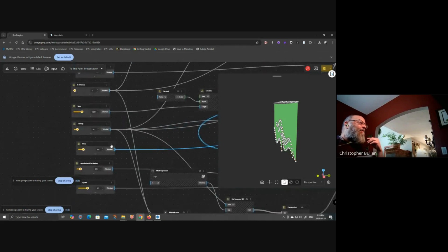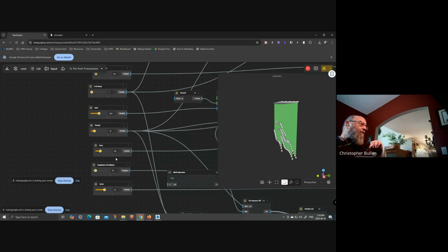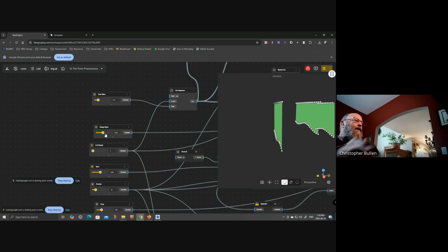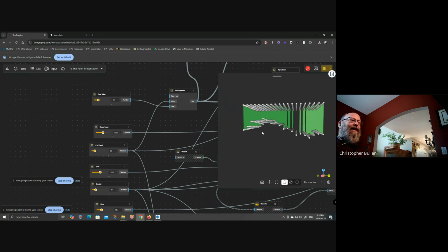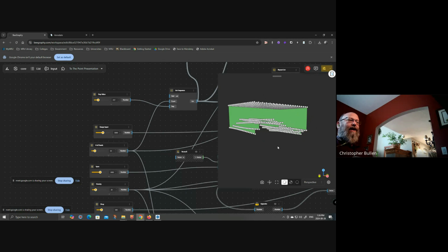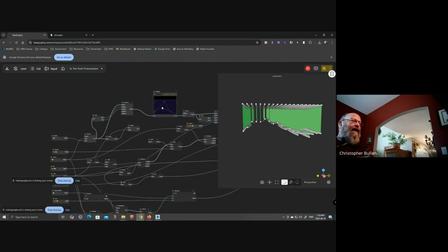Instead, for our amplitude, let's drop our amplitude down. Okay, and let's increase the number of panels. And we also want to be able to increase the range of this. So let's have this go over, let's say, 5 meters. And the number of panels, let's put that in to be 20 panels, let's say. So now we can actually see that the bottom of our panels here are following that curve, and they are following it because of the fact that we have, whoops, let's